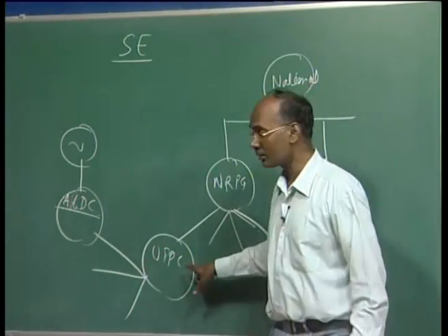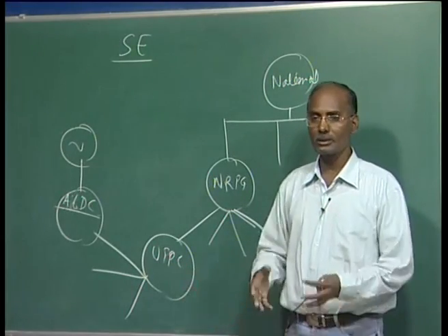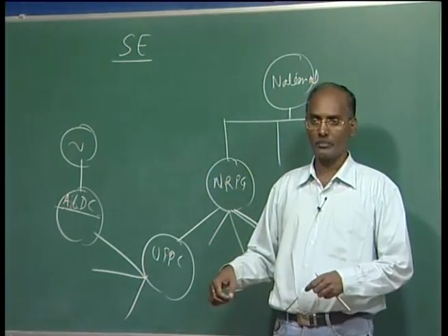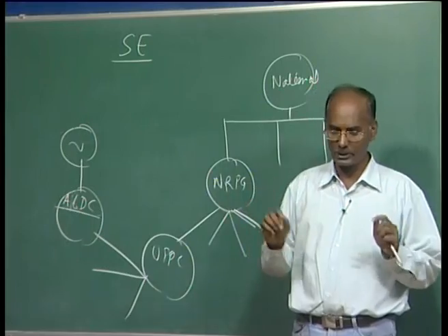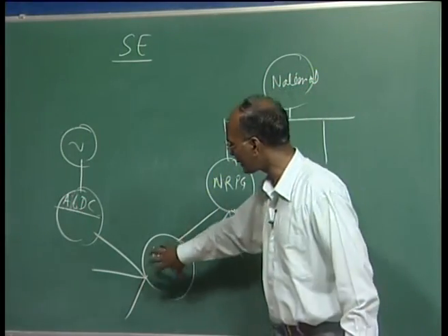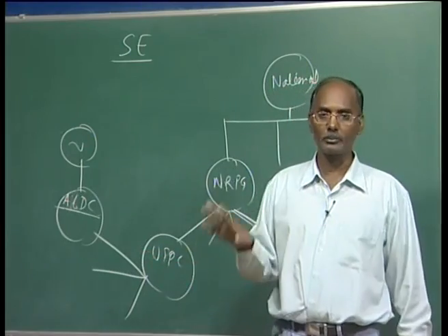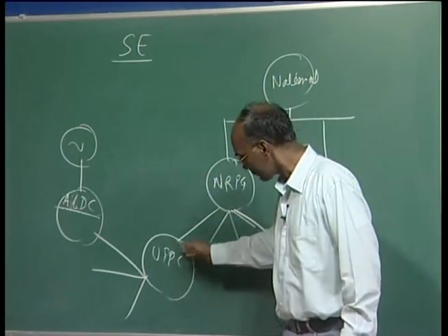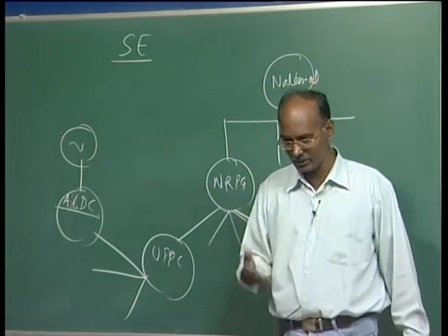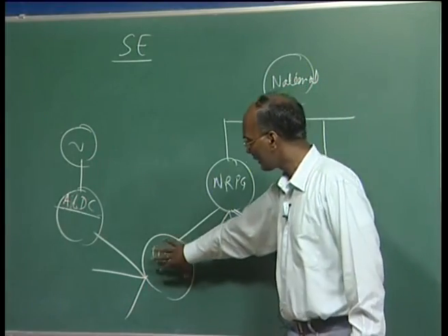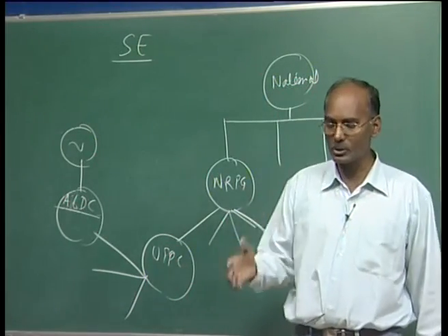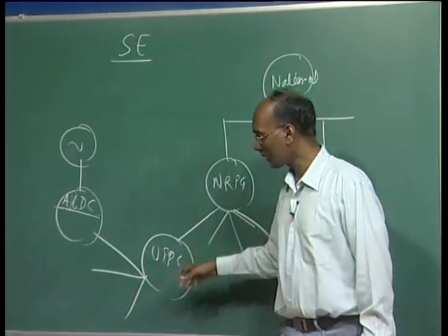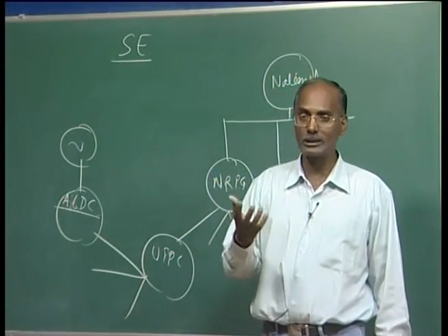Then he has to run the load flow, because right now that condition is not there. So he has to calculate the load flow based on the current loading etc., and then know what the voltage at various buses and the power flow will be. So the load flow is also required for the online operation of the system. We go for contingency analysis, meaning various outages etc., and then we see the security of the system, whether the present system is secure or normal or not. Normal operation also requires your load flow. You also require the load flow for running various things, like if you require stability analysis.